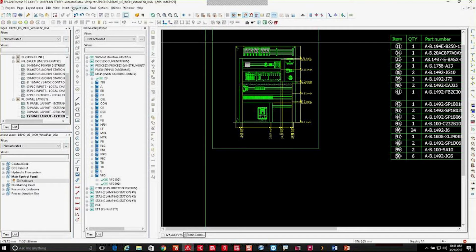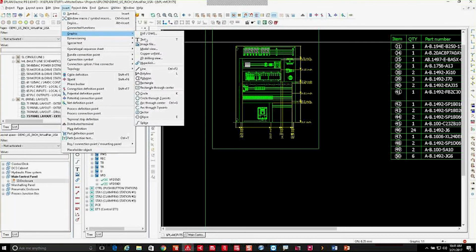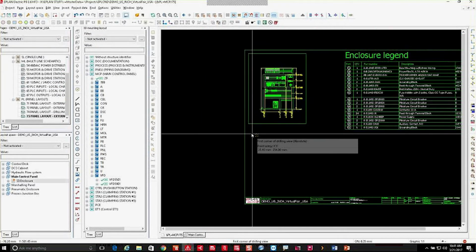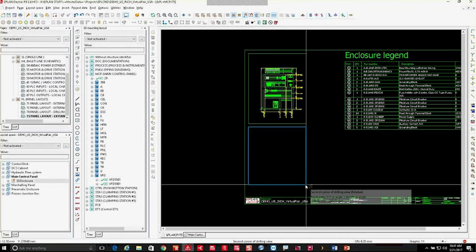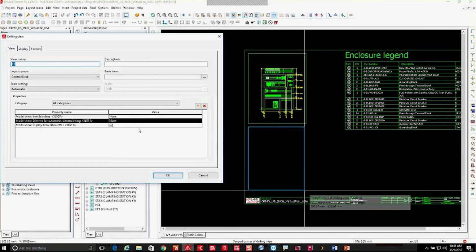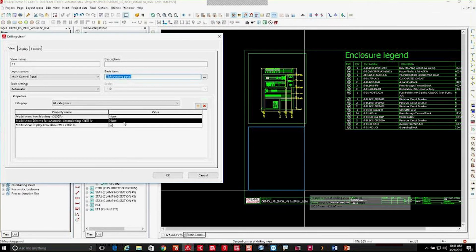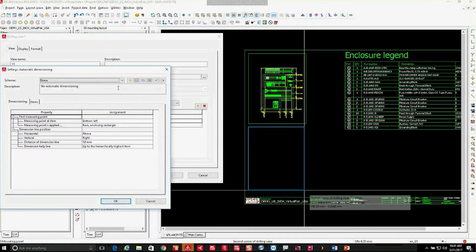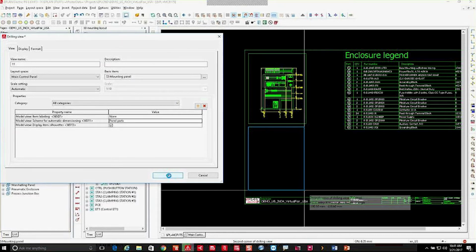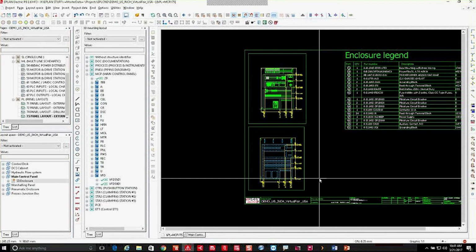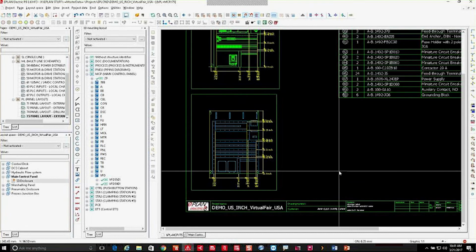So here, if I go ahead and insert graphics and 2D drill views, I can even add some drilling information for manufacturing purposes. And again, huge benefit in this aspect where all this information you're just clicking, dragging, selecting from options, very ease of use, menu options available, automated functions for dimensioning, and so on and so forth. All these benefits in the ease of use functions are saving you time. And of course, in our day and age, time equals money.